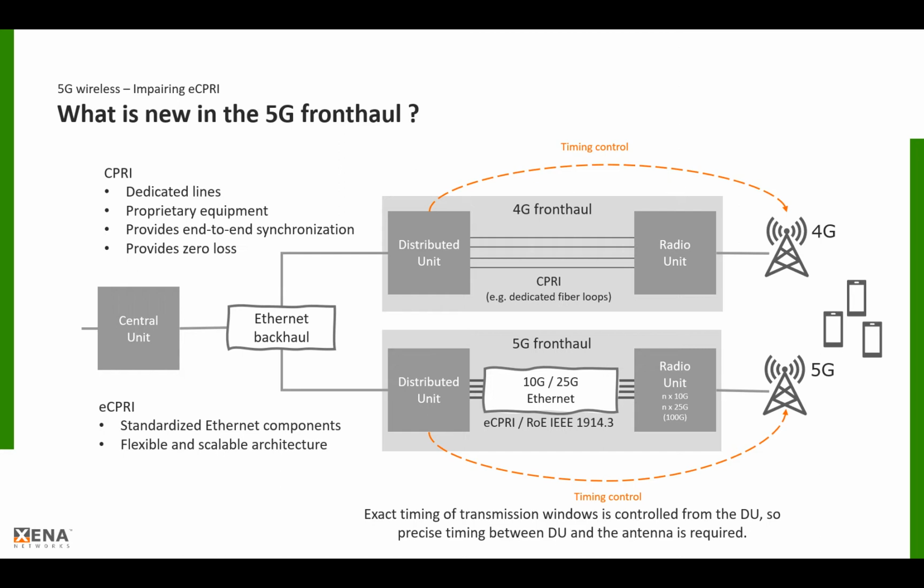In the 5G fronthaul, end-to-end timing is particularly important because antennas have dedicated transmission and reception windows which need to be coordinated with adjacent antennas to avoid interference. To add to the importance of the timing requirements, the exact transmission timing of the antenna is determined by the DUs, each controlling a number of antennas. Looking at the way the network is built, it's quite obvious why significant jitter on the eCPRI interface will complicate controlling the antennas from the DUs, and how loss of data or control frames will influence the user experience for users connected to the antennas from mobile devices. Keeping in mind that the extent of the fronthaul networks ranges from a few kilometers to up to 50+ kilometers underlines that the design challenge of these networks is indeed significant.